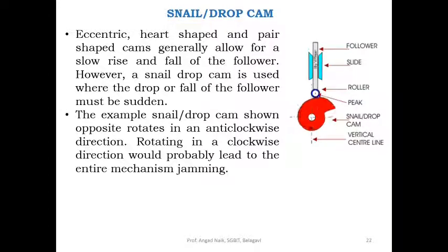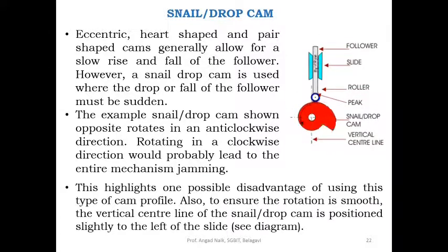Rotating in clockwise direction would probably lead to the entire mechanism jamming because the part which is dropped will obstruct the rotation of the cam. This highlights one possible disadvantage of using this type of cam profile, because of this jamming problem when it is rotated in clockwise direction.